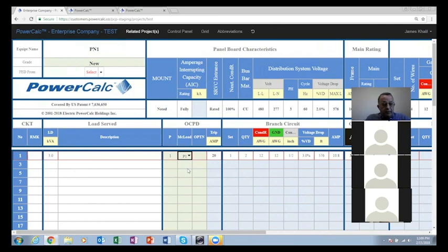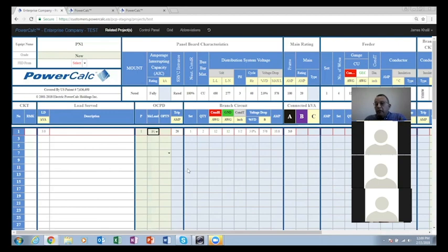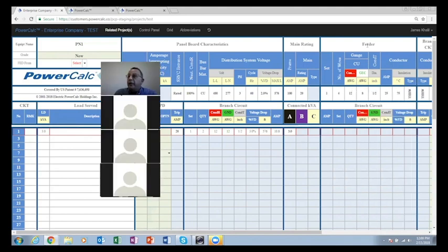Now let's go ahead and make it smaller again. You do that circuit by circuit, and you just put it into the panel. Once you add all these circuits, the system will generate the feeder for you. Right now, the feeder for that panel, based on this one circuit, is 4 number 12 and a number 8 ground in a 1/2 inch conduit. Of course, that's too small for a feeder panel, but as you add more circuits to it, you will see a larger feeder automatically calculated for you.